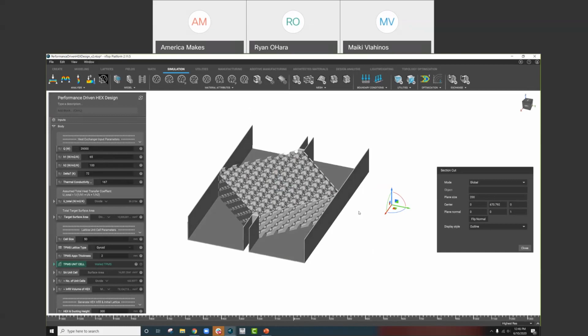So as far as wall thickness, once you've established your design from a structural standpoint, it'll come down to what material am I choosing, what machine is doing my printing, and therefore what are my minimum feature sizes. So how thin can I actually make my walls as far as manufacturing goes.